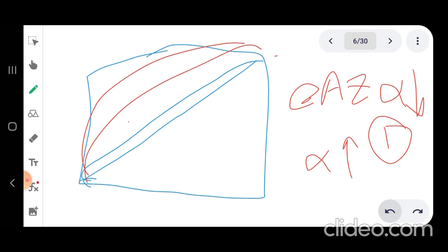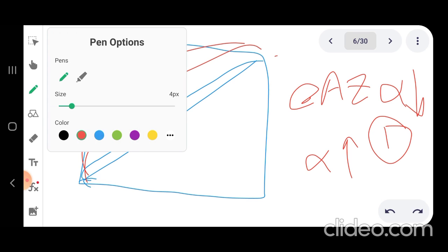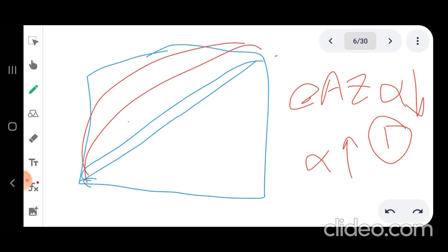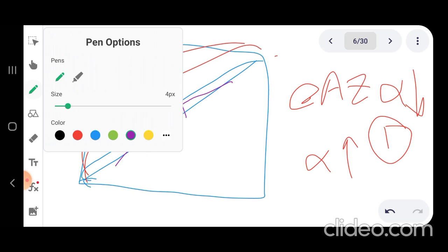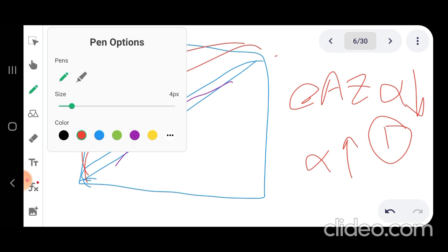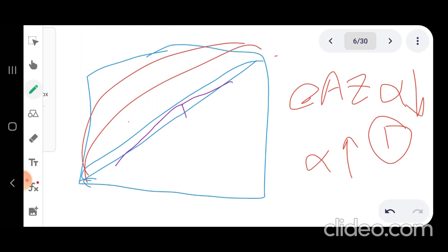So what happens after you draw the operating lines? As we know before, we draw the operating lines, the feed line, the q-line, and the other operating line. So what will happen? You will get too many stages, because the curve is tight. 1, 2, 3, 4, 5, 6, 7, 8, 9. Very tight. Then you can get, I don't know, 20, 30 trays. You need too many trays.